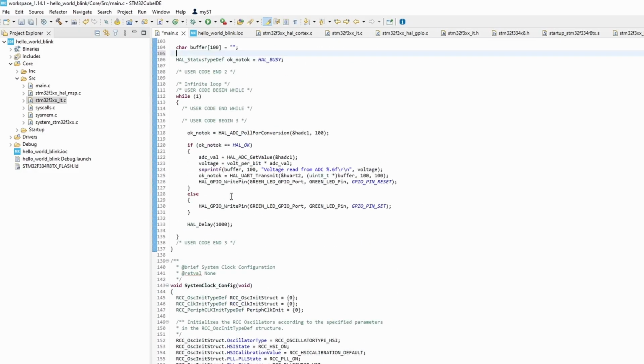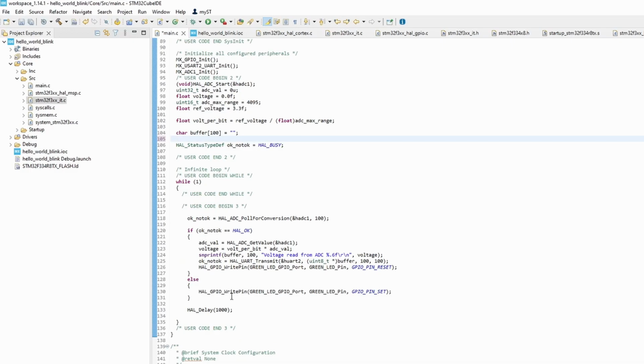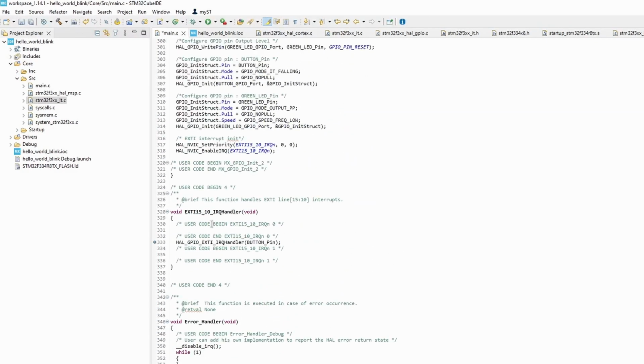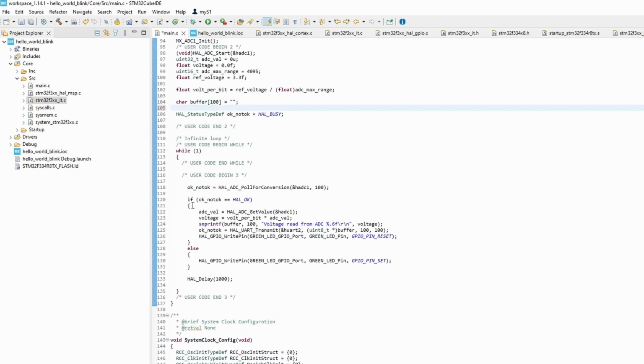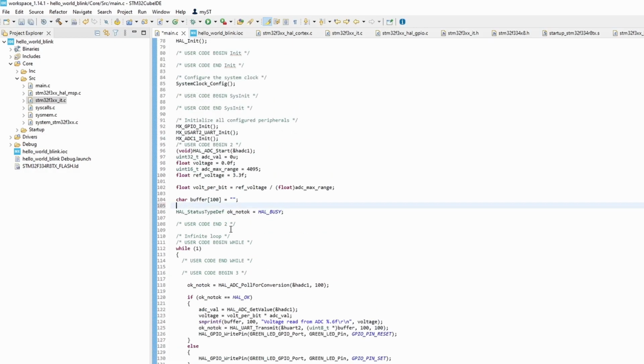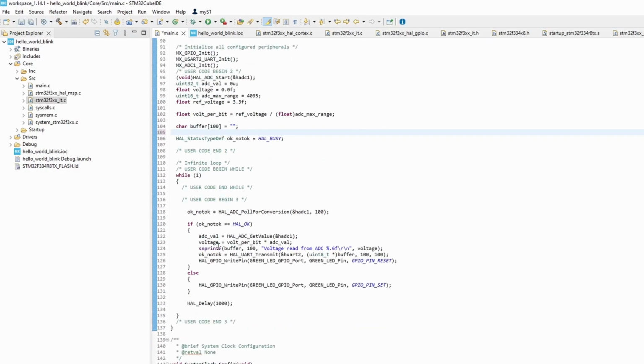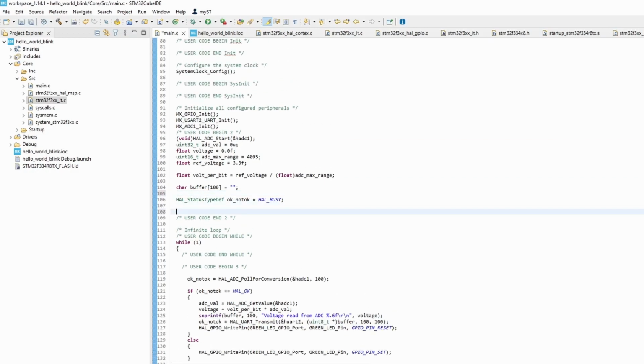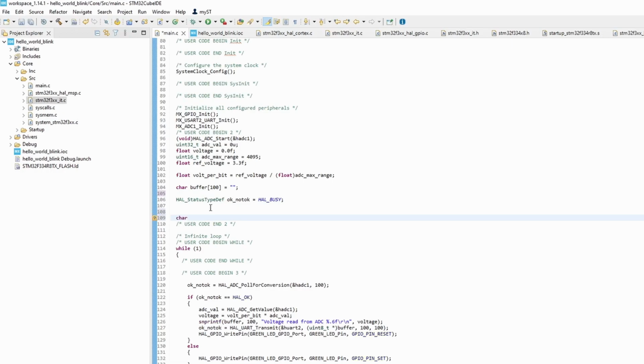As I was saying, I want a boolean flag because I want to just set a variable in the interrupt and then exit, and then in our while loop we can perform the code in here whenever the flag's set, and then we can set it back to false again. So what I can do is create a variable, a pointer to our hello world function or string that we can bring back from the first or the second tutorial.